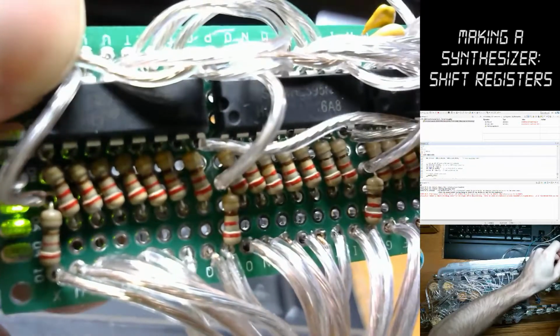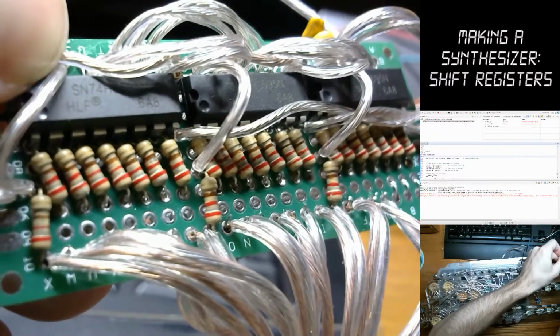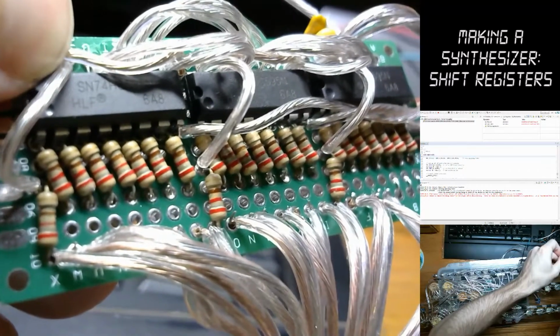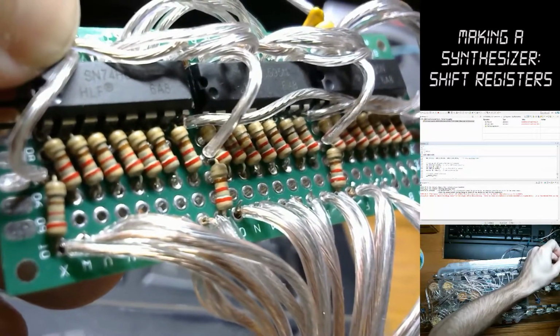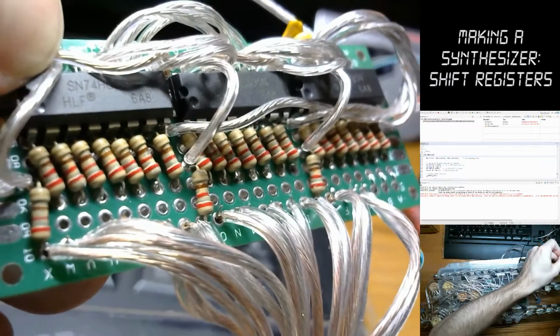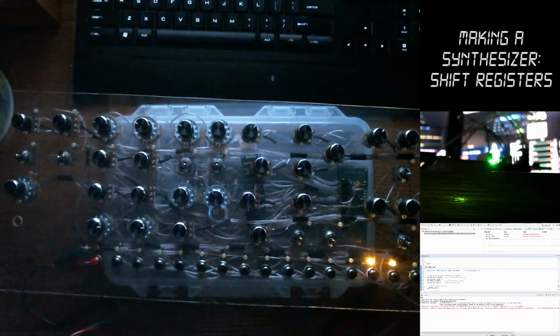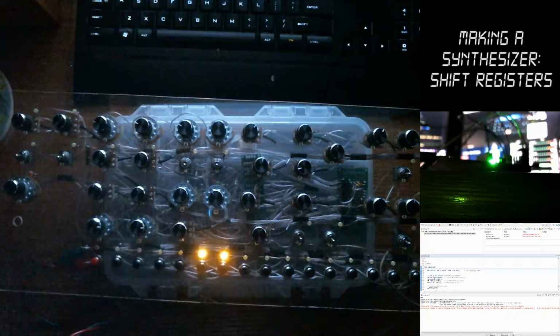So I have 3 of them tied together. The output of one shift register is connected to the serial input of the one next to it. So in this case, we get 24 discrete outputs that we can control individually, and with only 2 pins. Isn't that awesome?